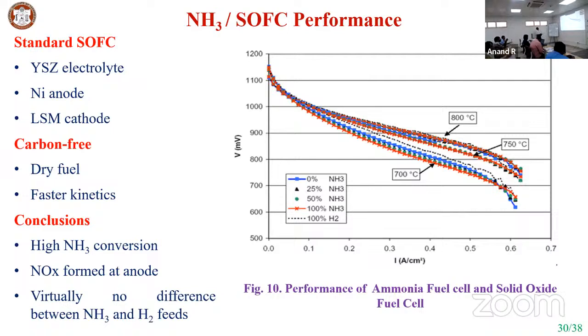hydrogen, 100% conversion of hydrogen from ammonia, based on the research currently available, the low temperature and medium temperature fuel cells are not suitable. We can go for high temperature fuel cell, preferably solid oxide fuel cell. I'm talking about using ammonia in a fuel cell for producing electricity directly. Suppose we are going for hydrogen from the ammonia, then you can go for PEM fuel cell. It's a proven fuel cell, low temperature fuel cell.